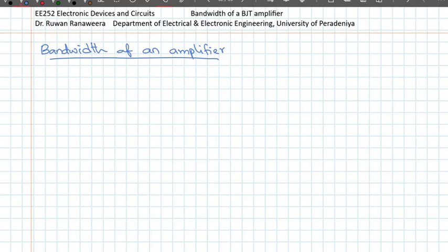So when we wanted to input a signal to a BJT amplifier circuit, what we did was to couple it through a capacitor to avoid any upsetting of the bias. So you initially have a bias, and then to couple an AC signal without having to worry about its DC component, we send it through a coupling capacitor. Now, what is the effect of these coupling capacitors? We did not actually look at it so far. We said it acts like a short circuit for the signal in frequency, but it's open circuit for DC currents,